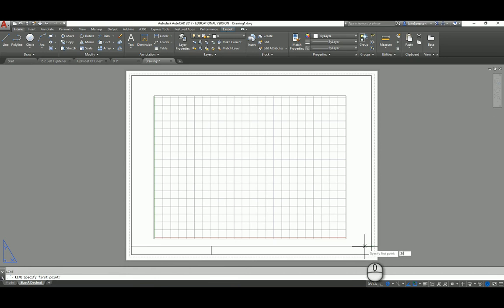This time it's 3/4. Notice I'm using fractions or decimal. AutoCAD's smart enough that it actually figures it out, that you're using a fraction versus decimal. I am now going to switch my offset dimension. Instead of using 3/4, I'm just going to simply type in what I want it to be. So these are skills that you guys will learn as you go.